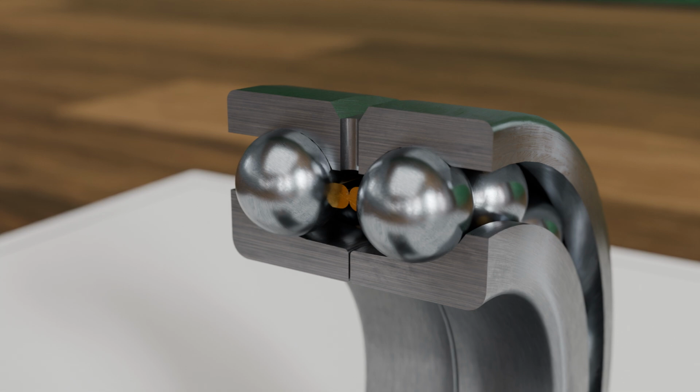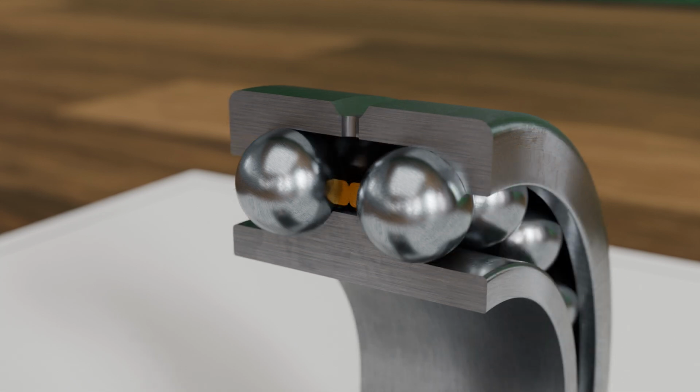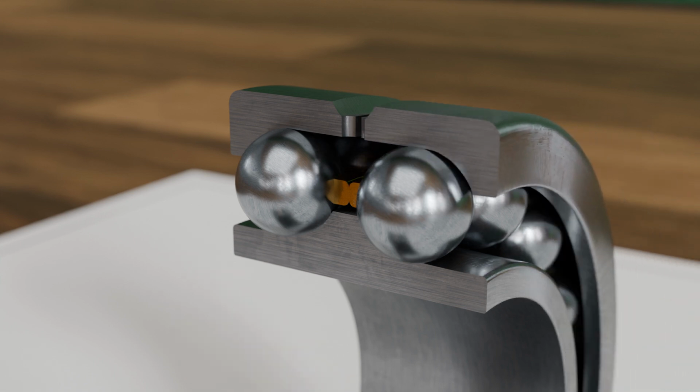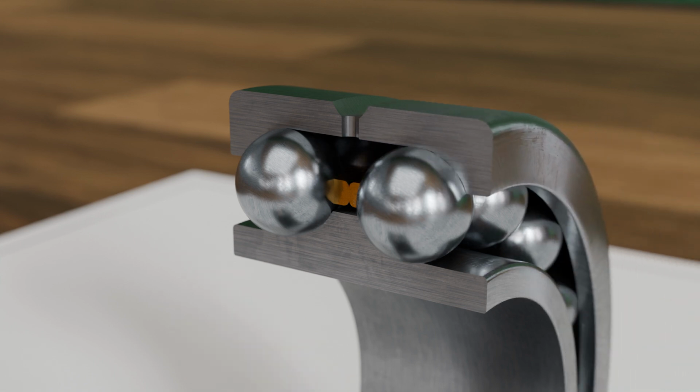In addition to double-row angular contact ball bearings with a split inner ring, there are also versions with a split outer ring. Due to their design, these can only be realized in the face-to-face arrangement. Such bearings are preferably used where the shaft is difficult to access or permanently installed, for example, in combination with split housings.